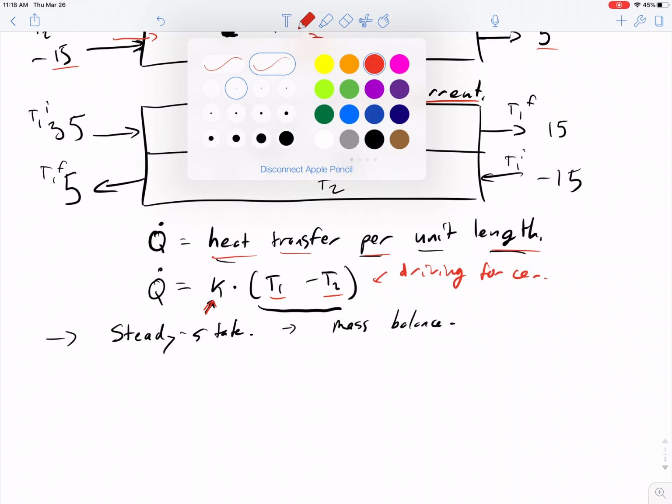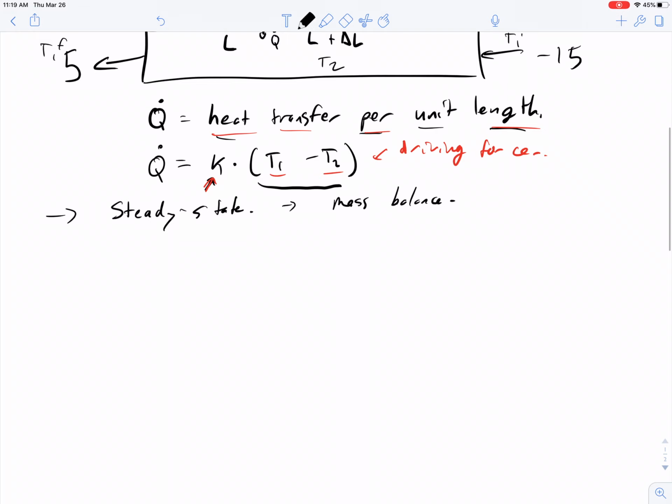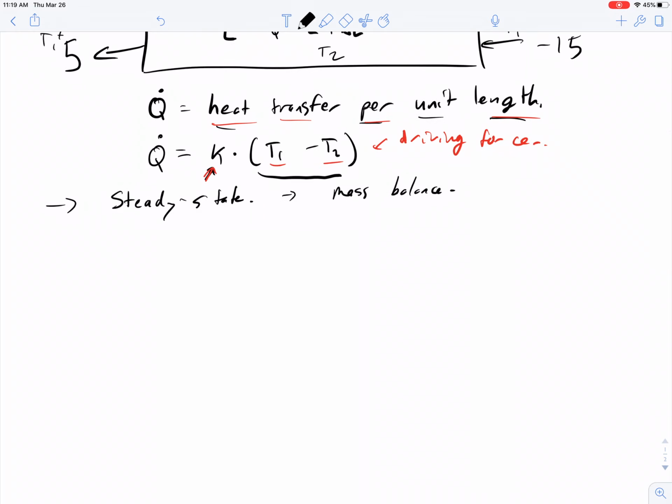So how do we approach a problem like this? We haven't yet done a problem that varies over space like this one. The way that we do this, and this is something that's very commonly done in fluids and transport courses, is to consider a small element here that has a unit width of delta L, a small interval delta L, that is extracted from the picture above. Then the interval goes from L to L plus delta L, and you look at what's happening inside of this small